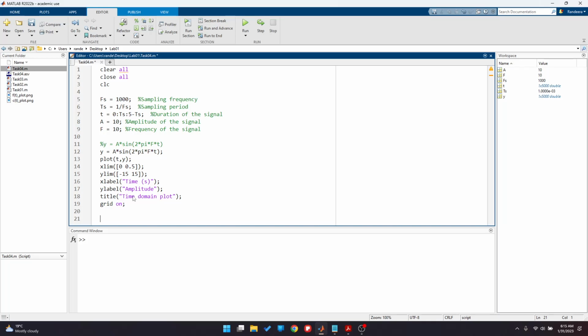So convert this frequency of 10 hertz to the frequency domain, where in this frequency domain graph, we should obtain a peak corresponding to 10 hertz. Now, there are many ways of achieving that, all based on the FFT command in MATLAB. And these different methods produce graphs of slightly different nature, but all get the job done.